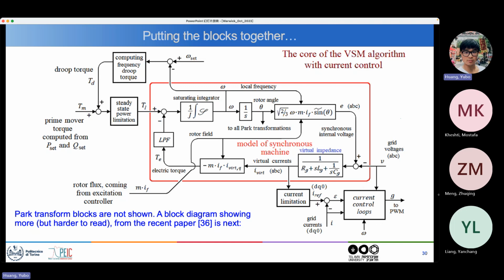Now, in a real system, there are all kinds of ways to do that, such as power system stabilizers that you put on the excitation control and so on. In virtual synchronous machines, or in a grid in which a part of the machines are virtual synchronous machines, you don't have, not all.